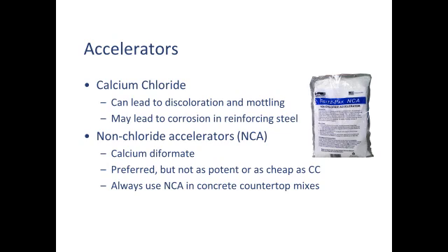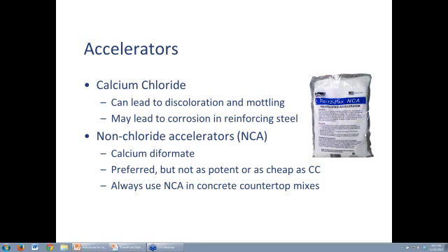I've used non-calcium chloride, specifically a calcium diformate. Fritzpack's NCA is one brand that is a calcium diformate that does not affect the color at all. It's more expensive and is not as potent, and it doesn't work as fast, but it is the preferred accelerator if you're going to use a chemical accelerator. And what a lot of folks do when they're grouting their concrete to fill in the pinholes is put an accelerator in their grout so it hardens faster.